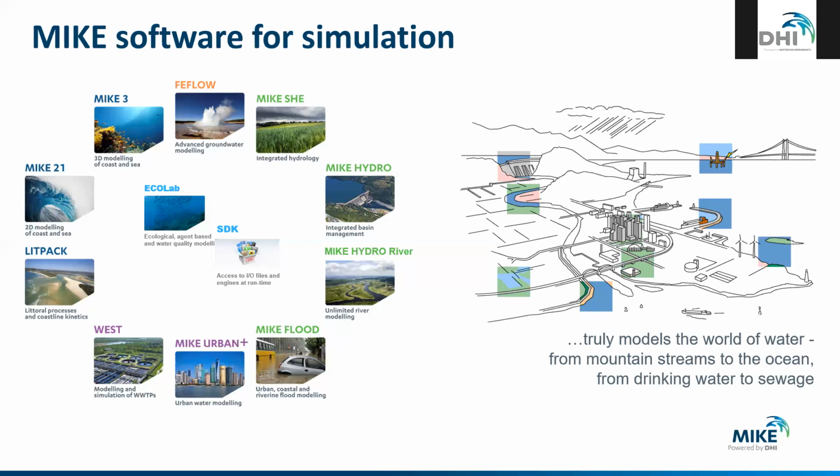It's a layered model that has flow exchange between the vertical layers. And we've just actually released update number 1 to our 2019 software. And in the release for MIKE 3, we actually have a full non-hydrostatic 3D solver now, which comes as part of the MIKE 3 software.